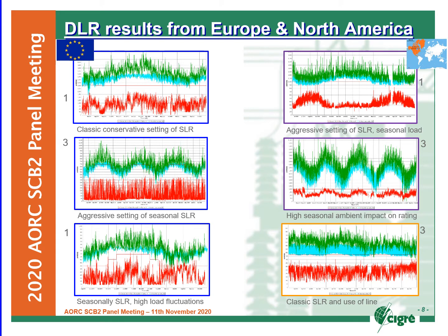You can see that the dynamic line rating is generally affected by seasonal weather characteristics, meaning there's more capacity due to cooler conditions in winter compared to summer. The difference is starker in some regions than others. The exception is the bottom right system, which shows no strong seasonal patterns throughout the 3 years of observations. This is a system in the tropics.